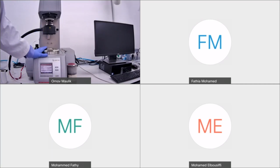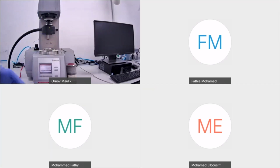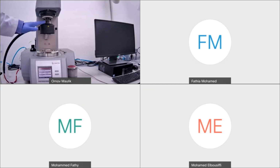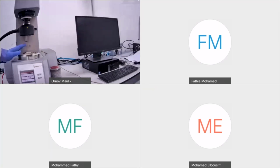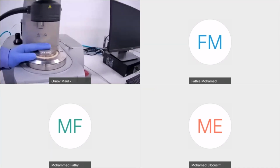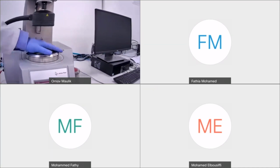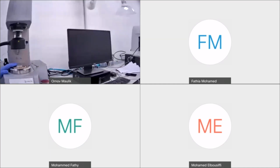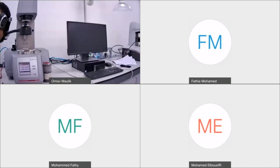We have heating from the top and heating from the bottom, so in order to maintain complete thermal homogeneity, we heat the sample from the top as well as from the bottom plate. This is the bottom plate where we usually keep our sample, and it is also Peltier temperature controlled. It can also go from -40 to 200 degrees Celsius.